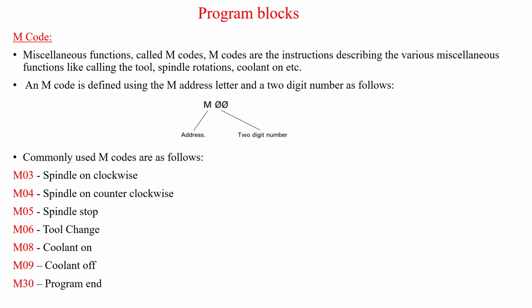Now coming to M code. G code is clear? Yes, sir. So like G code was a geometrical code, M code is a machine code. G code includes every parameter of the coordinate system, na, the x, y, z coordinates. M code includes every coding of the machine-related things.